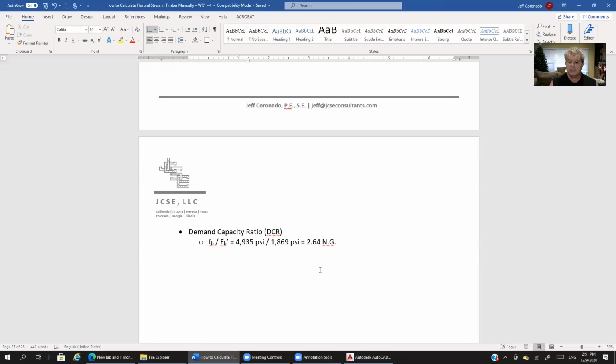This section, as designed currently, does not work. Whatever it is that we had, like I think 2x6 at 24 on center, that won't work. Something needs to change, whether it's the span, the spacing, or the grade of lumber, because as of right now, that design doesn't work.